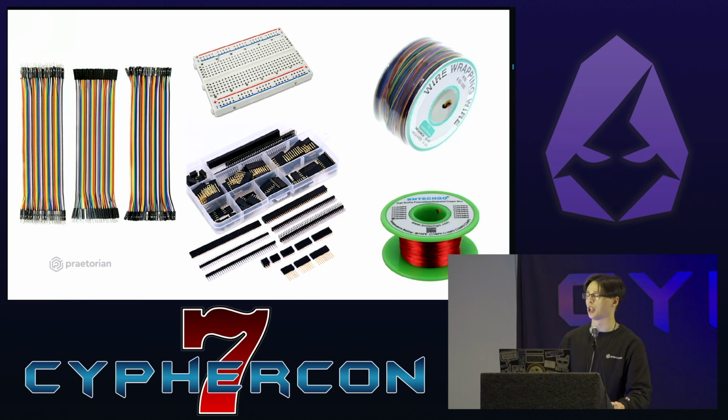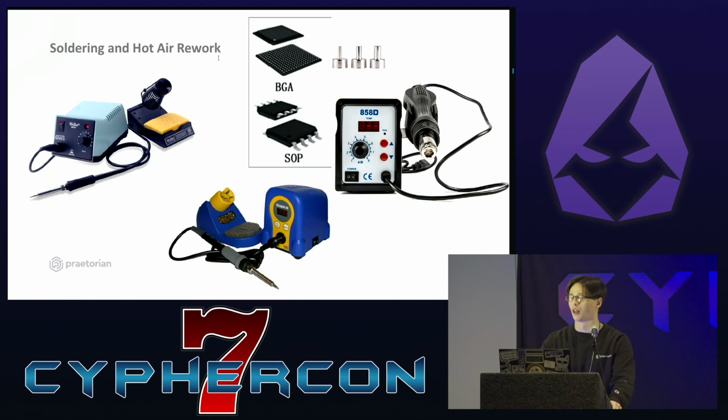for particular applications. If you search for wire wrapping wire, that's a really good source for getting a lot of these thin wires very cheaply. And then there's also this enameled magnet wire. A little bit harder stripping that enamel coating off of it. You can use sandpaper, you can try to burn it off with the tip of your soldering iron, or scrape it with an X-Acto knife. Lots of different approaches, but that can come in handy as well. But I'd say the jumper wires you're seeing a lot more often.